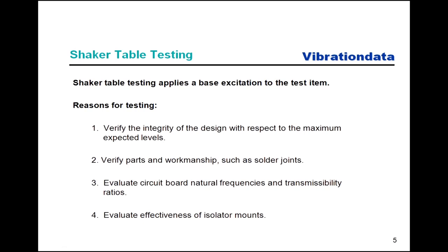I guess a particular concern is more the cold temperature, where these isolators might become hardened, and they would lose their compliance, and the natural frequency would go up. And that would be typically the case for some rubber or elastomeric thermoplastic type isolator. And if that's the case, we might have to do something like a wire rope isolator.